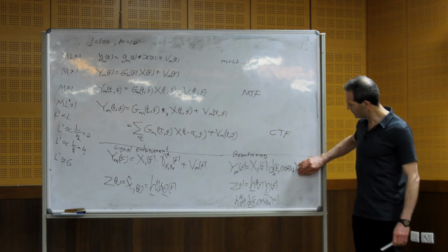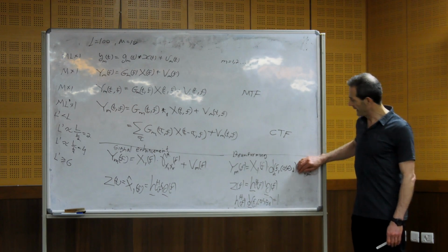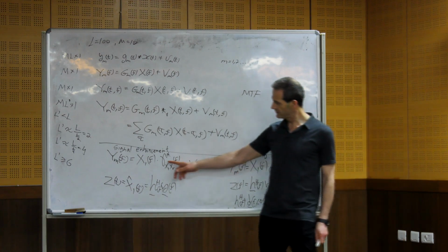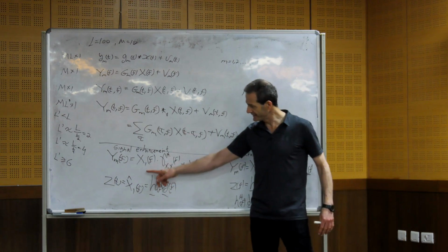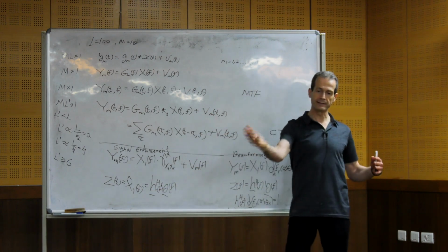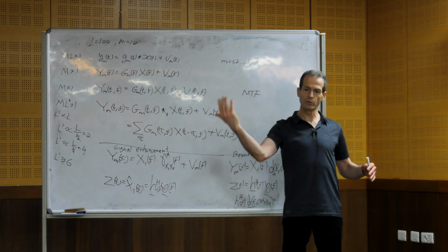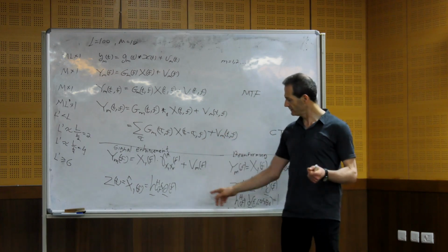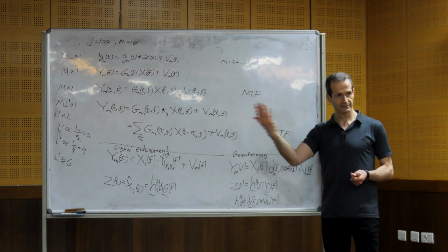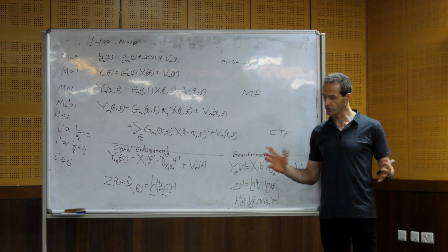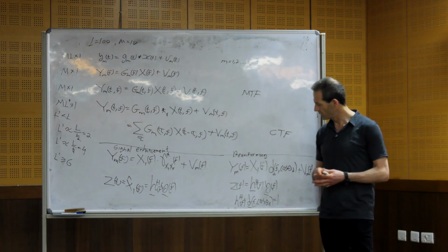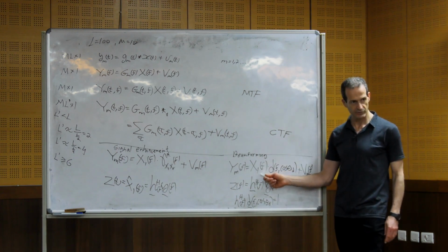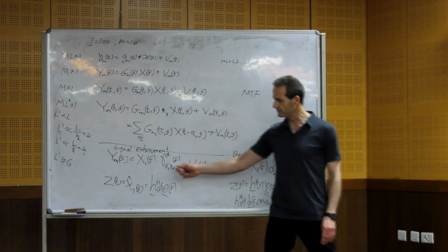But suppose that we don't have noise, and we have some reflections from surfaces. Here, using this filter, we combine the direct path and the reflections into a stronger signal. Here, we suppress the reflections. We don't combine them with the direct path. So suppose that we don't have noise. We have less signal in a reverberant environment than we can have here.